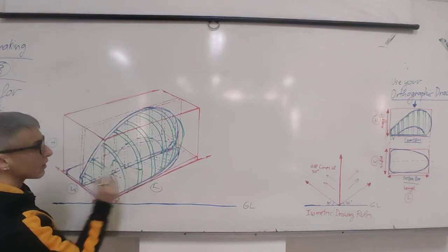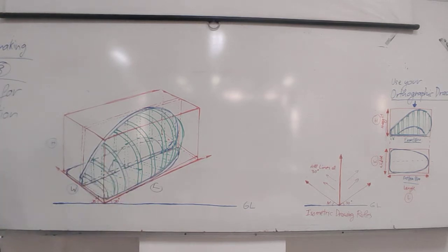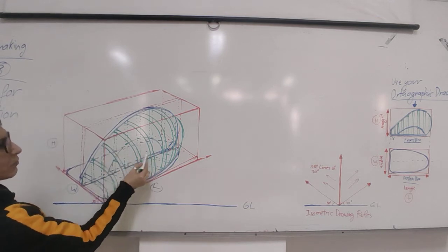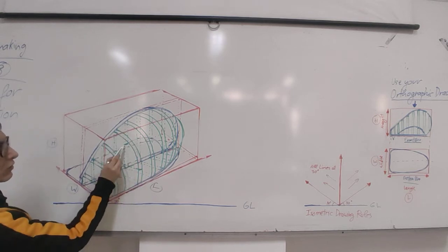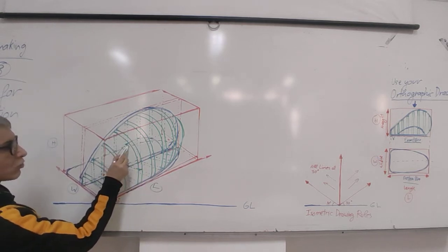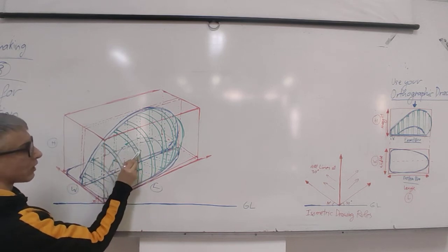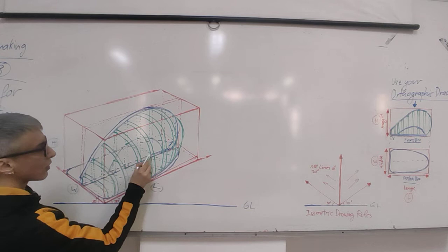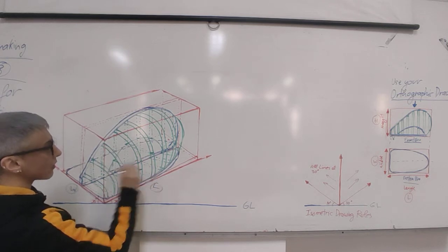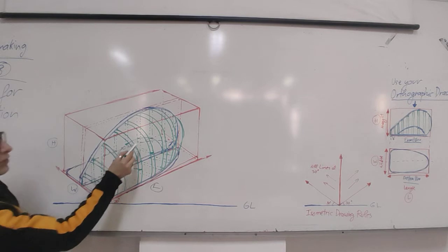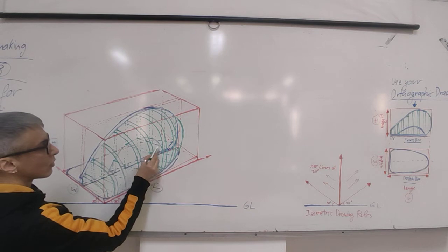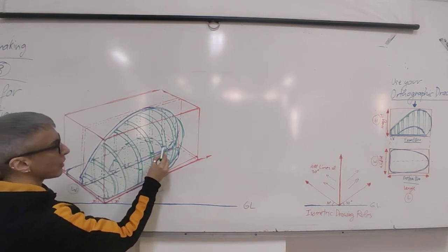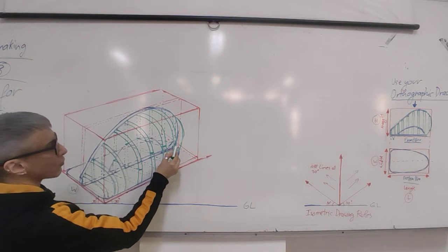So here on this piece, here is the starting point, for example, of the change of the shape. Then on this next piece, where is it going to be located? Look, this piece here is this piece. So this point must be located somewhere here. You just take lines out which are parallel to the rest, and you locate where it's going to be located here. Here. And the third piece, again, 30-degree lines out. Where is it going to be located? Here. And to the fourth one as well. Where is it going to be located?